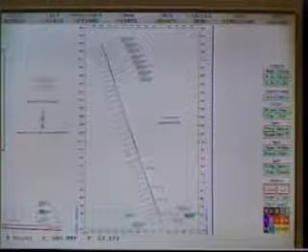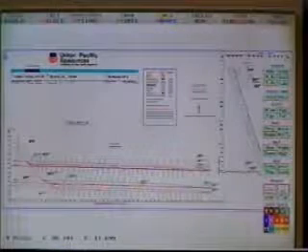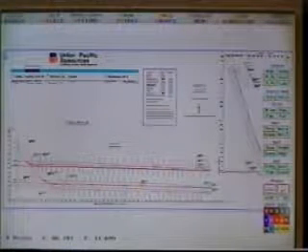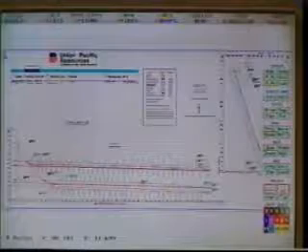With a bent housing positive displacement motor, a well-designed bottom hole assembly, and MWD capabilities, it's possible to minimize wellbore deviation and stay on course simply by changing the tool face orientation as needed. But as companies have begun drilling longer horizontal and extended reach wells, they found that simply staying on target may not be good enough once we reach the productive interval.